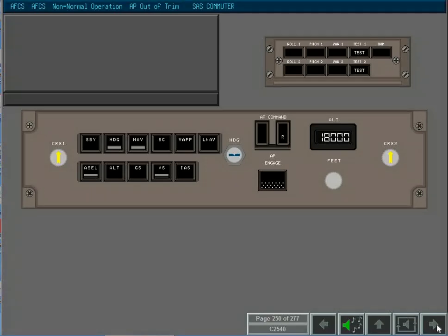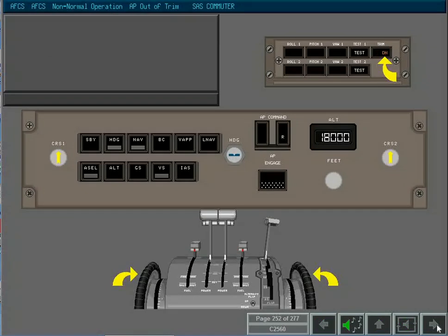When engaged, the autopilot provides automatic elevator trim signals to aerodynamically balance the aircraft. Elevator trim removes the need for continuous torque from the elevator servos. If the autopilot goes out of trim for more than 12 seconds, a Level 2 alert is presented, and a trim light annunciates on the Automatic Flight Control System status panel. The trim annunciators up and down indicate the direction that requires trim.